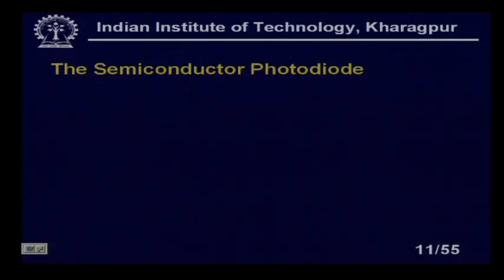Now, semiconductor photodiode. Now we talk about only the photoresistors. So, light dependent resistors we are also calling them, but more applications in instrumentation you will find in the semiconductor photodiode. Photodiode and phototransistor are almost the same. In case of phototransistors, I will get some amplification, but the time constant is large, whereas in the case of photodiode, current is small, but the time constant is small.